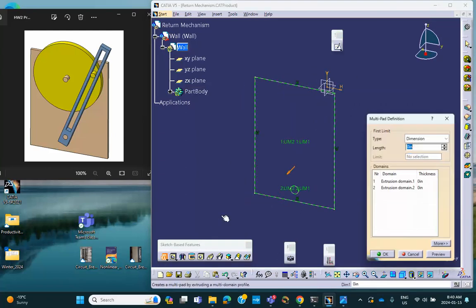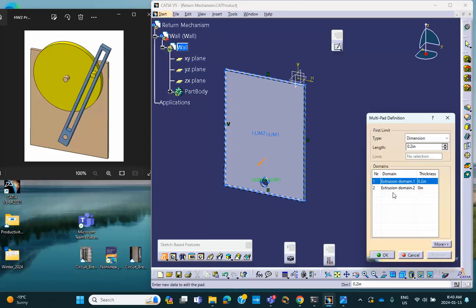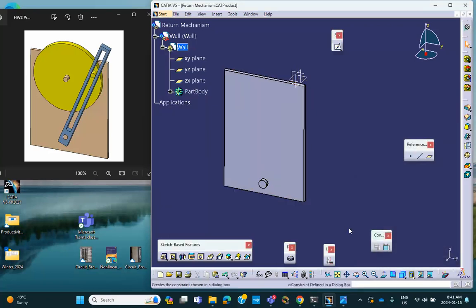If I do a pad, there will be a hole down there, which I don't want. So this one is going to be the big rectangle. Let's make this thing 0.1. If needed, we're going to change, or 0.2. Let's see how it looks. Yeah, that's good. And this one obviously is going to be more than 0.2. We'll make it 0.4. There.